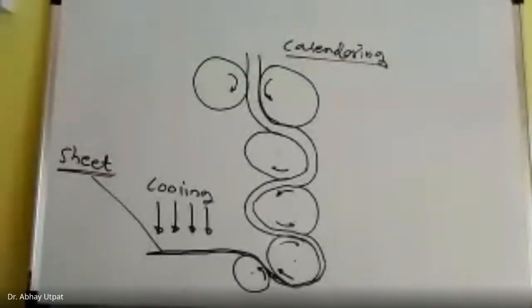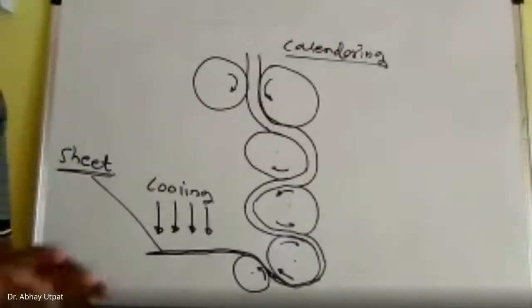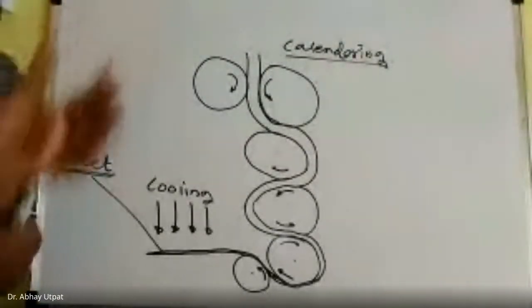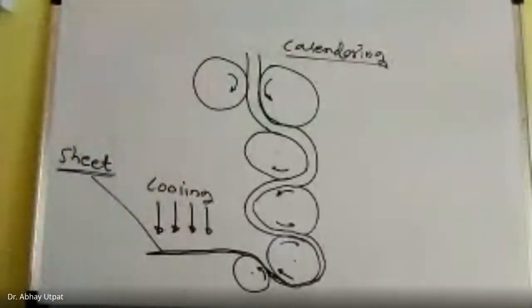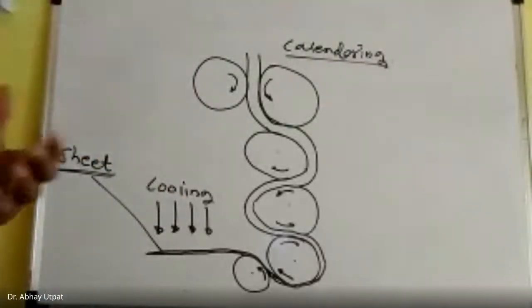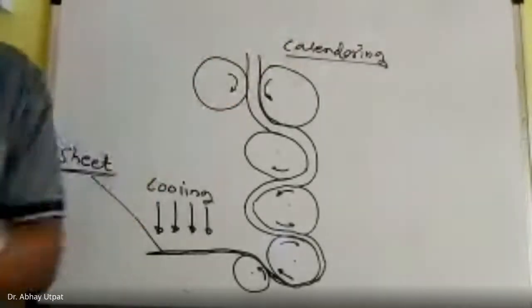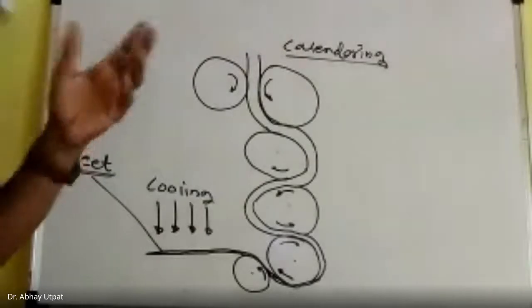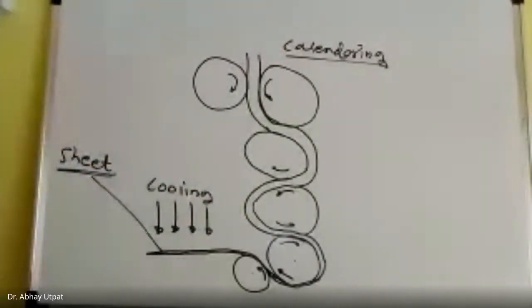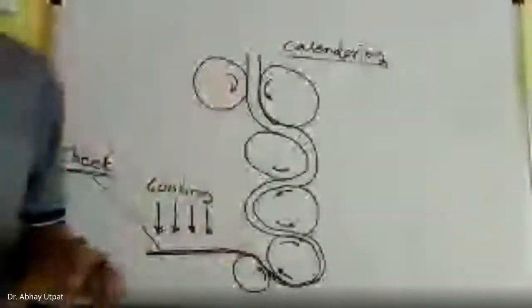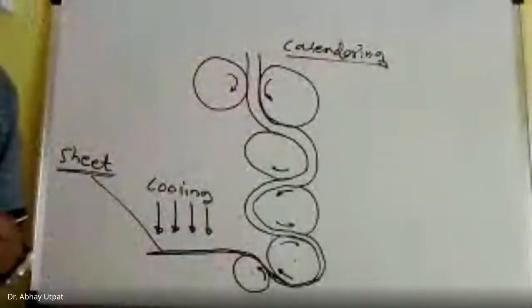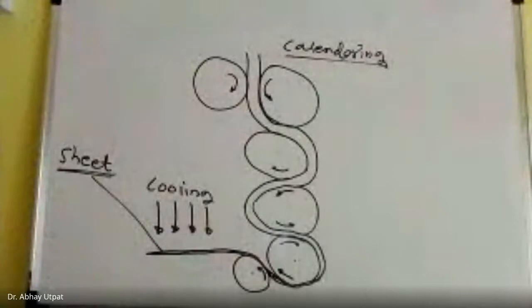Extrusion molding is produced by an extrusion operation, where the plastic material is completely confined in a closed cylinder and is forced to open through a small opening, so it will take the same shape as that of the cross section. Number of cross sections are available in the extrusion process, and as per the cross section, the product may be finished or semi-finished. The best application is your pipe. Pipe is one of the final products produced by the extrusion molding process.